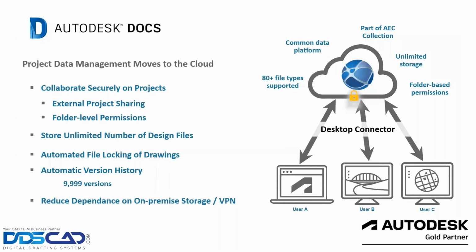However, if you're using AutoCAD or Civil 3D like we do, what happens is, and I've tested this out, one person opens it, and if the other person opens that same file, it doesn't notify them that the file was open, and so there's no file locking mechanism for any other file format but Microsoft stuff, right? Basically it starts making copies of every user who's ever opened up the file, and it makes a complete mess of your OneDrive folder, okay? Obviously, if you integrate SharePoint, that's a whole different avenue, but that's truly integrating it completely with your whole operating system and everything, which most people don't do unless you're a really large organization.